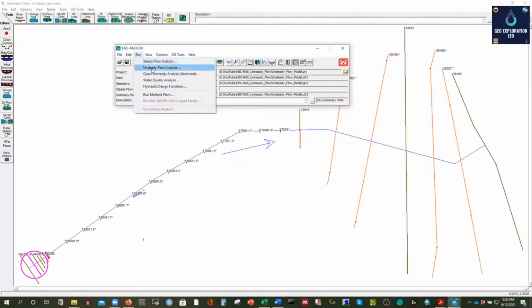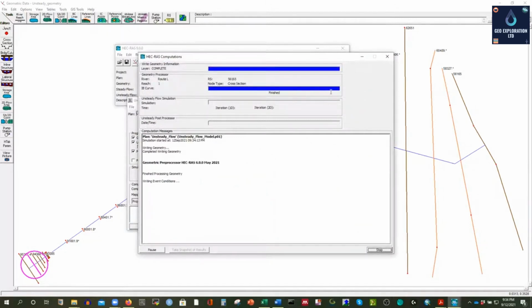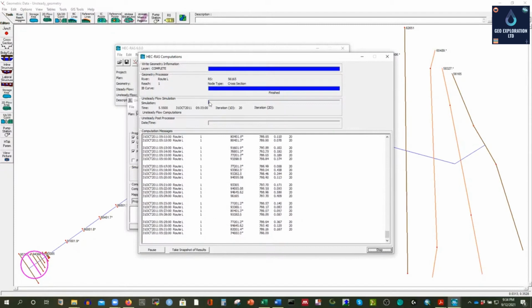And here, the main thing we need to know is, if I reduce this time step from 5 minutes to 1 minute, and you can even go to 0.1 second, I'm not going to do that. So the default one is 1 minute. And if I run this, you'll see what the time step is. I'm going to hit run, and it is checking the pre-processing. Everything is okay. It finished pretty quickly. There is no error, but you can see that it is not even going to see the 1st of November. It's just running for the 4th of November. Can you see that? It's going to take a while.